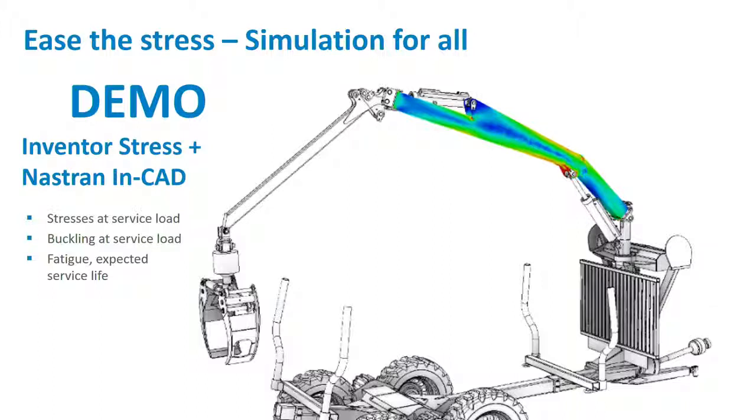Can that be done in Inventor, all of this? No. We can't make any buckling in Inventor. We can't make any plastic deformation in Inventor. We can't make a non-linear static stress analysis if we look at what happens at ultimate load and it might start to collapse, but maybe will not collapse fully.